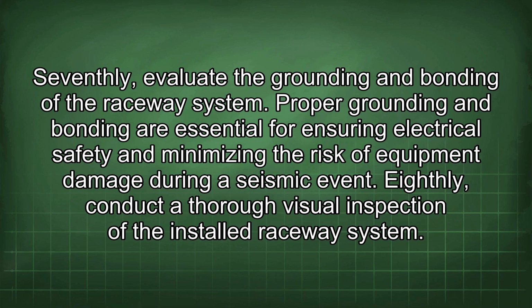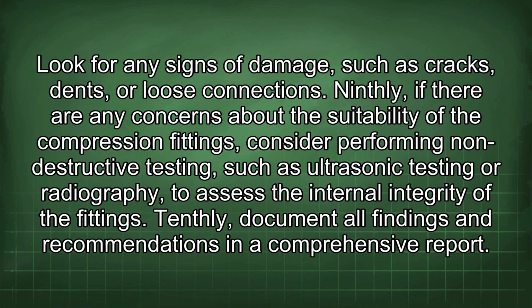Seventhly, evaluate the grounding and bonding of the raceway system. Proper grounding and bonding are essential for ensuring electrical safety and minimizing the risk of equipment damage during a seismic event. Eighthly, conduct a thorough visual inspection of the installed raceway system. Look for any signs of damage, such as cracks, dents, or loose connections.